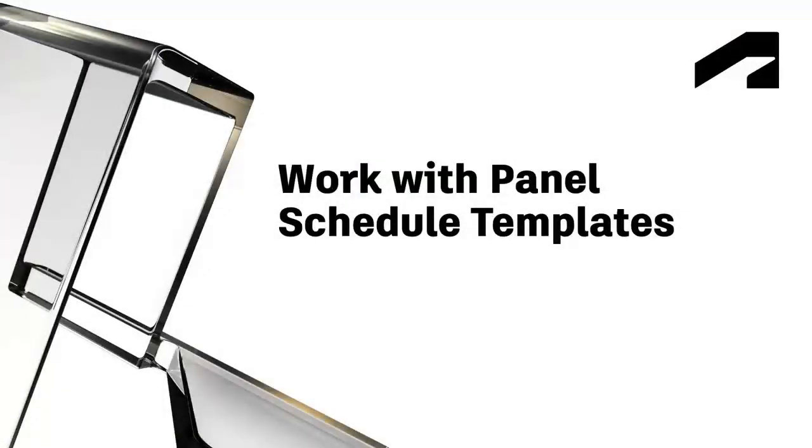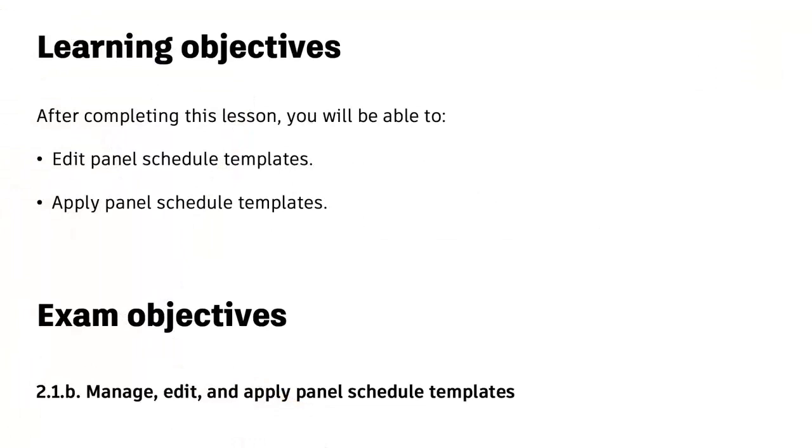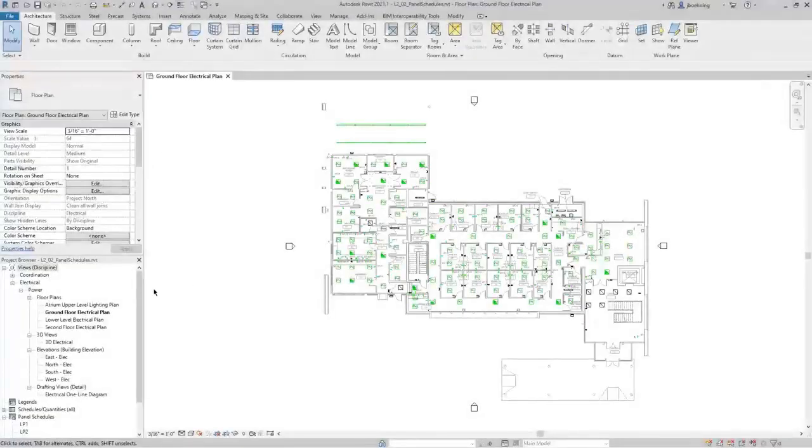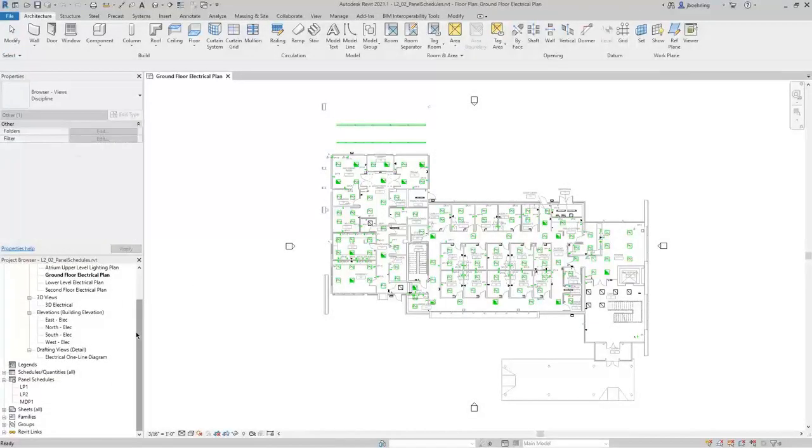In this video, we will cover editing panel schedule templates and applying panel schedule templates. In this project, there are 3 panel schedules. Panel schedules are based on templates, and the panel schedule template controls the formatting and the information that appears in the panel schedule.